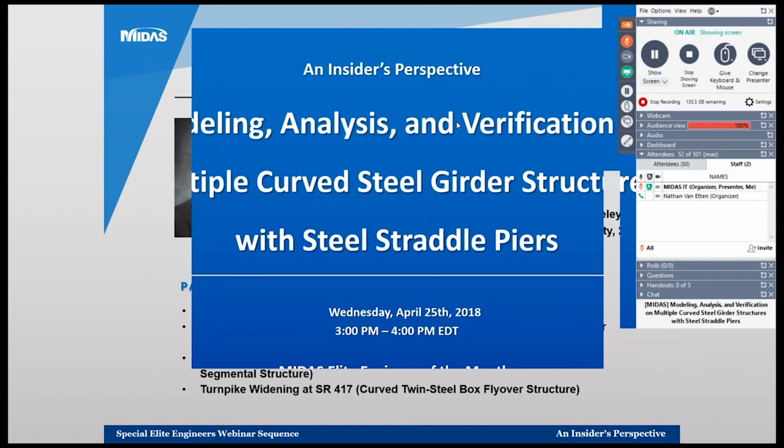However, it can be done in MIDAS, and it does have merit if you're not liking the results that you're seeing. In fact, that was something that we kicked back and forth, but as we started to play with the numbers, the stiffnesses we were getting for our particular bearing pad were quite large, so we decided to omit it.